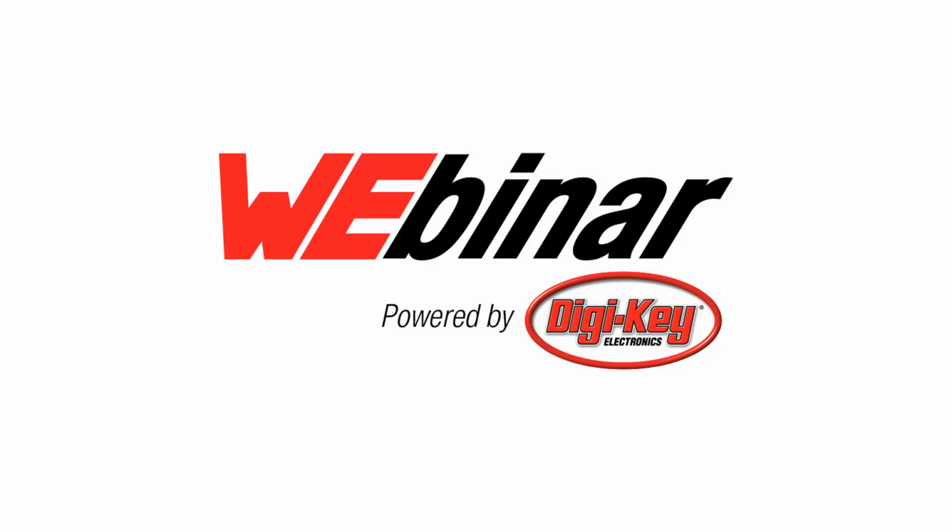When you Z wind, you reduce that in half because you've only gone one layer, you come back to the beginning again, so you actually reduce the voltage difference between the two layers in half. And where you can reduce the voltage, you'll have less capacitance. So you do that when you need low capacitance, and it really doesn't matter what size the transformer is.